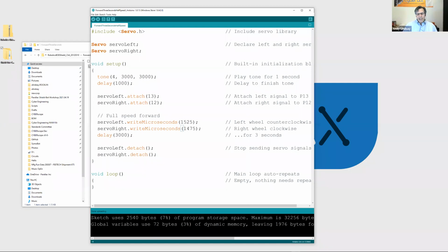For the third time, everybody remember to have yourself and your students unplug the barrel plug from the barrel jack on the Arduino when you're done for the day, because otherwise it will continue to drink a small amount of current all night or all week, and that can cause difficulties with the batteries. By the way, rechargeable and alkaline are fine.